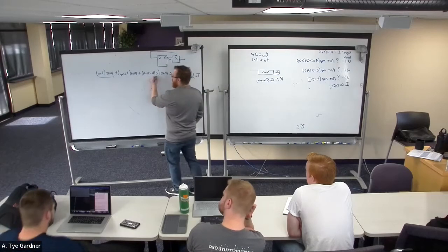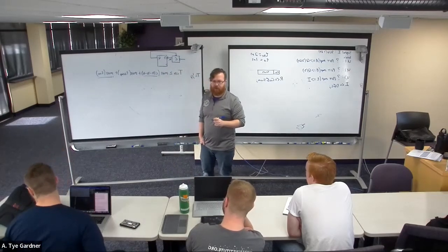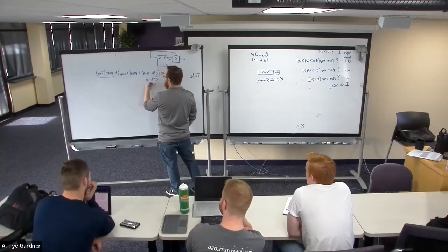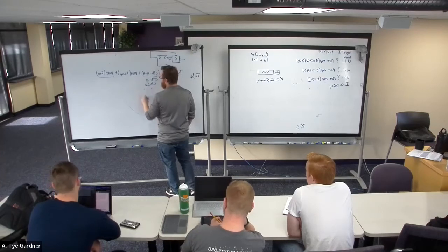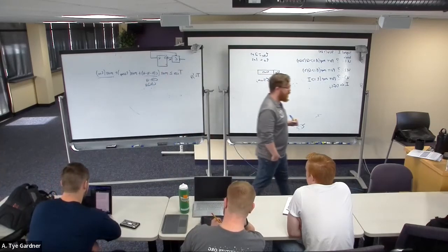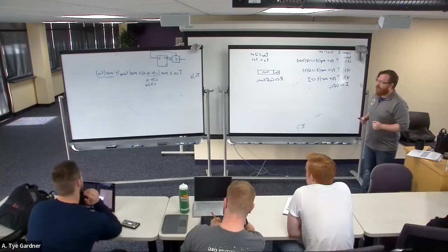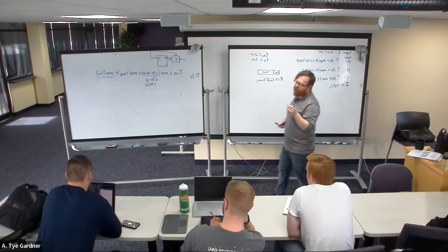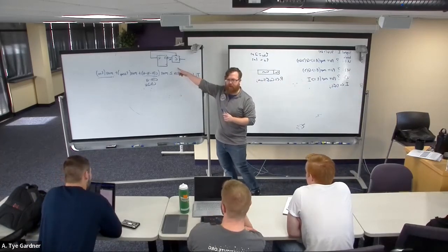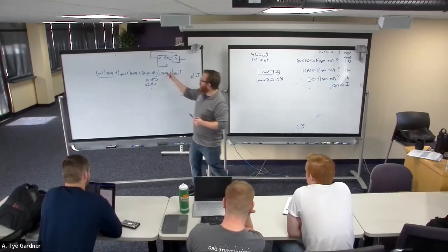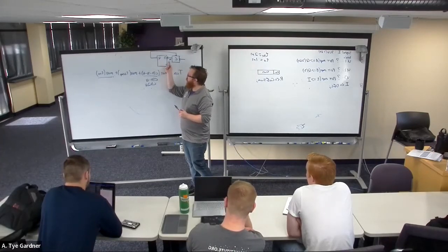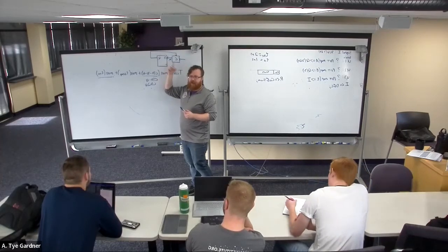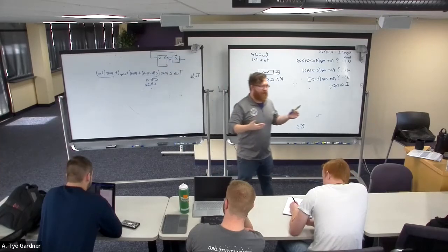However, there's a new issue, which is called your clock to Q, which will also be written as clock Q or clock to Q are the most common ways to see this written. Now what the clock to Q is how much time does it take between the rising or falling, but in this case rising, right? There's no bubble, so that means this is a rising edge device. How much time does it take between the rising edge for Q to update alpha? What's the delay?